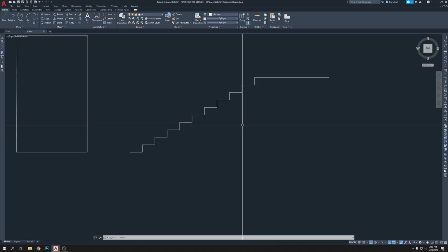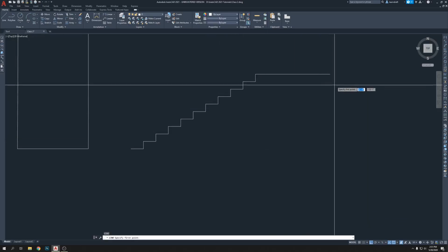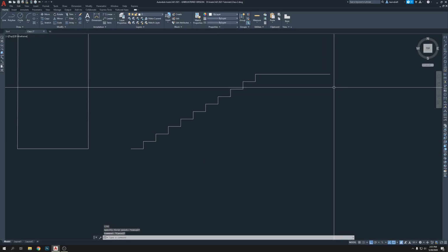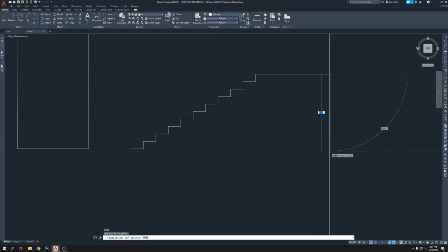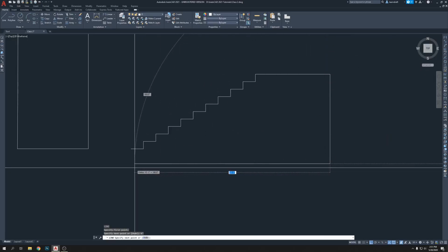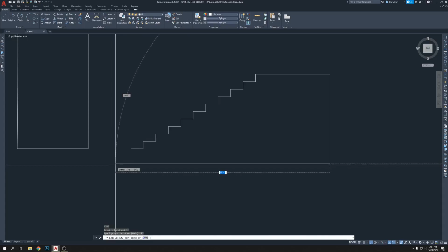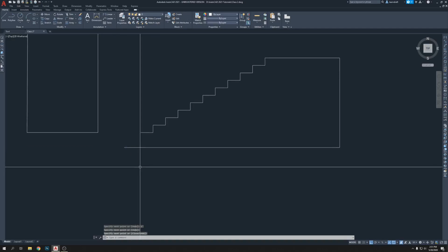We're going to do extend. Okay, so now we're going to draw a line here. L, enter, click here and bring it down, let's say 6 feet, 6, and the feet key next to the enter, and then bring it this way. Go a little bit extra, no problem, or you can go a little bit extra and just click without dimension and press enter. So click and enter.